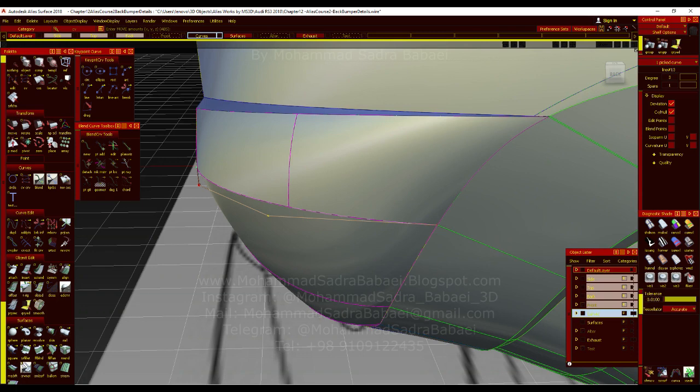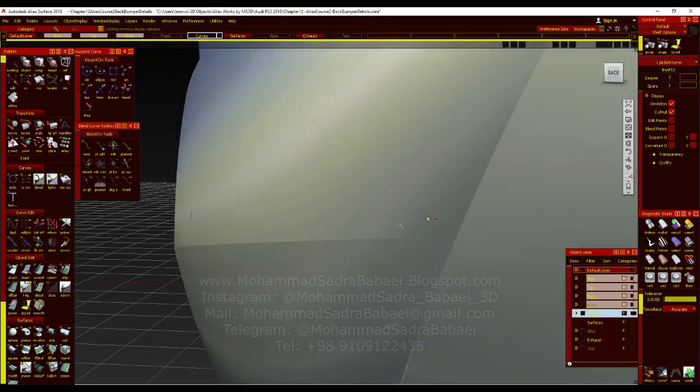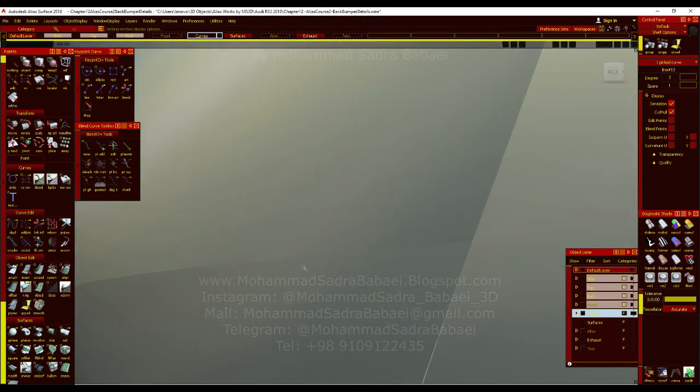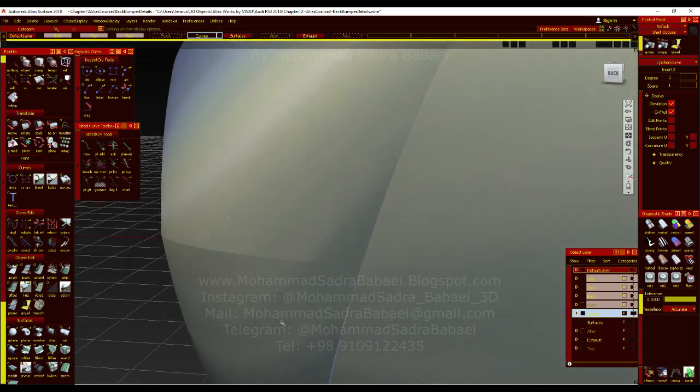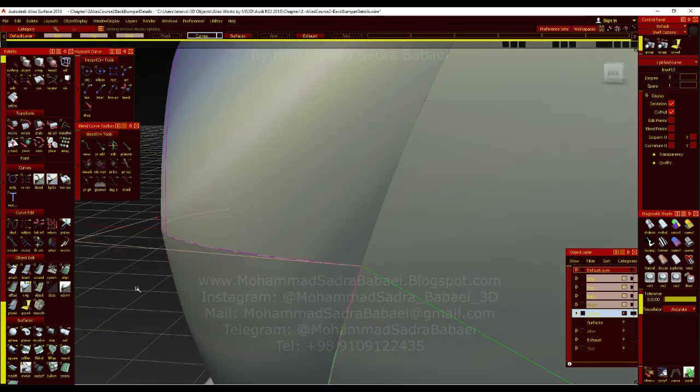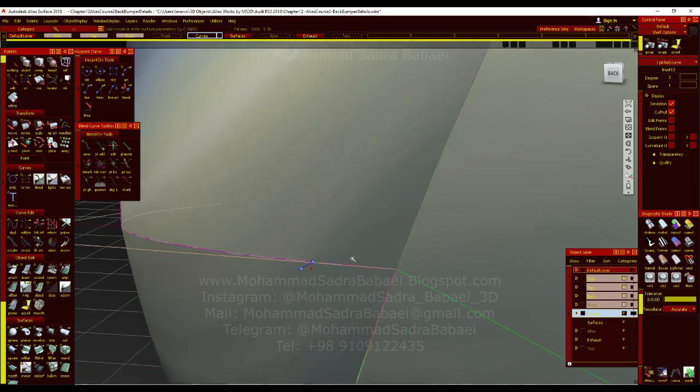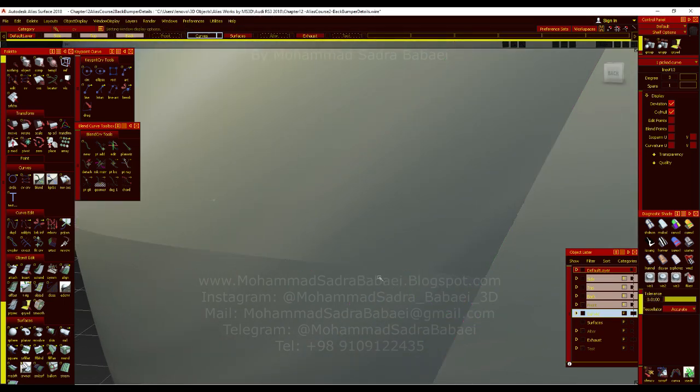because if you don't move this, you can't add a fillet here. As you see, the tangency is still here, so you should move it again. Move it more and more, until you get only one line with the positional touch.